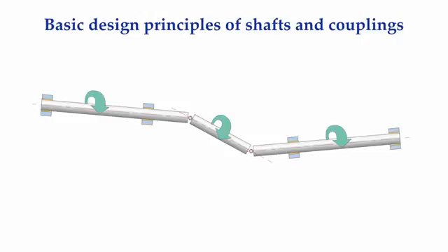Realizing that, it would seem to make sense that we should try to minimize the torture that the flexing points have to undergo. If we extend the center line of rotation of the shaft on the left toward the flexing point at the end of the shaft on the right, and show where the flexing plane is there, and conversely extend the center line of rotation of the shaft on the right toward the flexing point at the end of the shaft on the left, and show where the flexing plane is there, and look at the gap or deviation between the center lines of rotation at the flexing plane on the right side of the coupling, and at the flexing plane on the left side of the coupling, we now have a great visual image of the amount of misalignment that is occurring at both of the flexing planes.